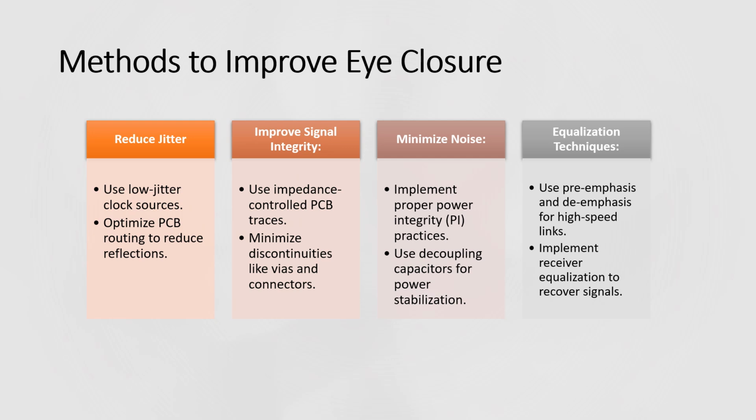Then eye diagram can also be improved by looking at your power integrity analysis. An improved power delivery network can help you implement proper power integrity practices. You can use decoupling capacitors for power stabilization.